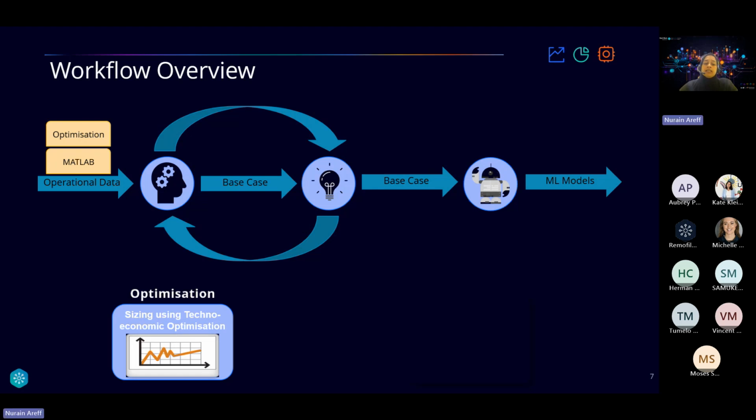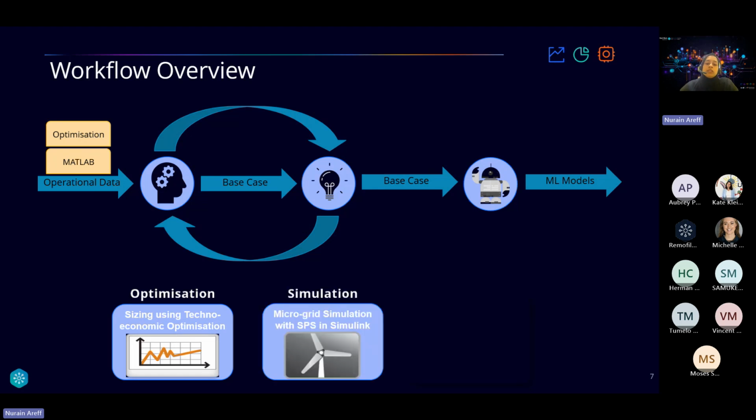Then after we get the sizing of our PV and our battery components, the next step would be our simulation. This is where we're going to incorporate our PV and battery system with the grid as well as the load. The toolboxes that are used for this include Simulink as well as Simscape. And with Simscape, you have additional features and domains such as Simscape Electrical and Simscape Battery.